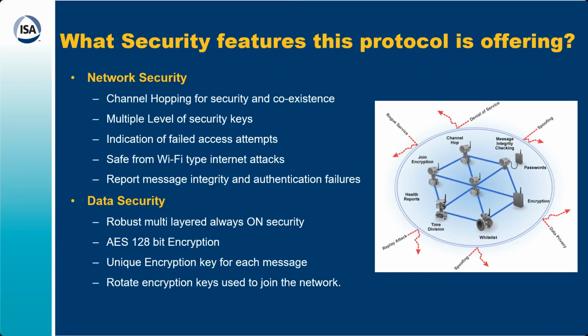As far as data security is concerned, it has the advanced encryption standard, 128-bit encryption is available with you. Every message has a unique encryption key, and that's how it is rotating the encryption keys while joining the network, while connecting to the network. All those advanced cybersecurity features are available with WirelessHART, so that the network gets secure.